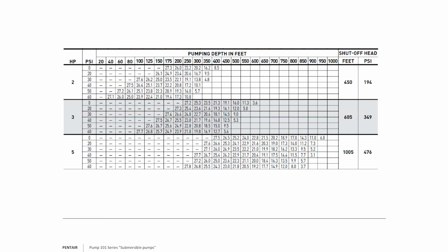If we look at the chart, remember we have total dynamic head. So we look at 350 because I don't have 354 to look at here. And again, 0 PSI. And at 0 PSI, at 350 feet, 23.5 gallons per minute. So we're a little bit over the mark. But again, at that point, we have the tank for a buffer.